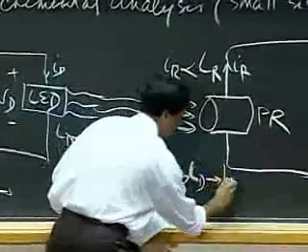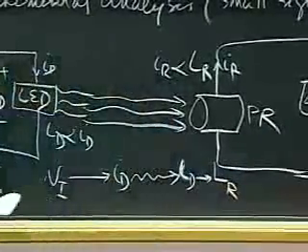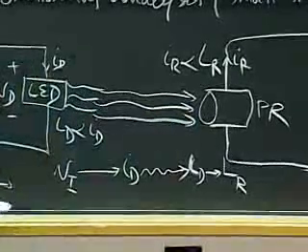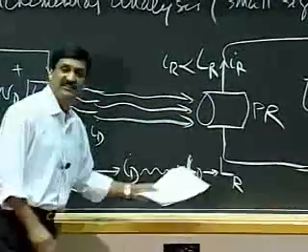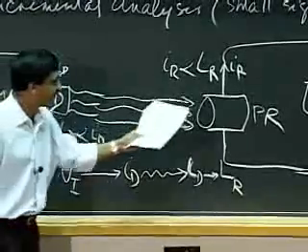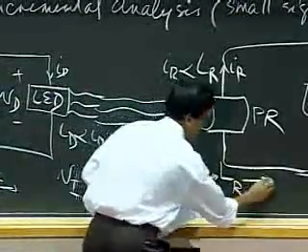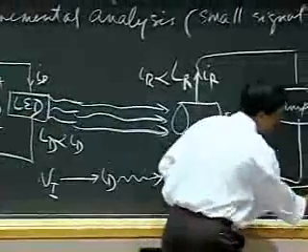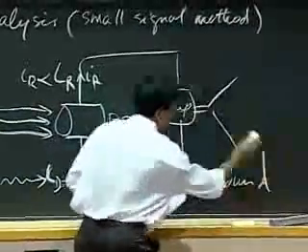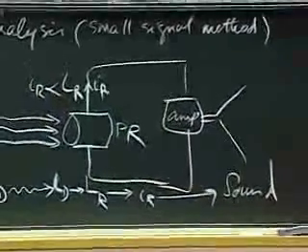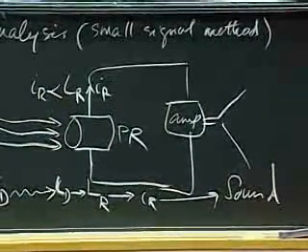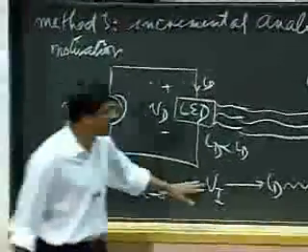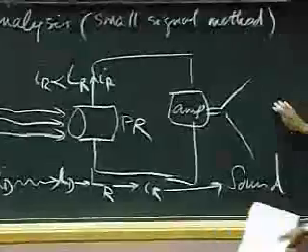This in turn gets attenuated somewhat and is received at the photoresistor, and I get some intensity LR impinging on that device there, and that in turn produces a current IR, and then IR is amplified and goes through a speaker and so on and produces sound. So notice that using this chain, I've taken the music signal here and I'm playing it here.